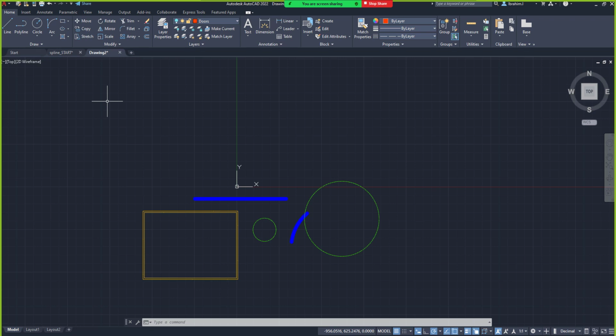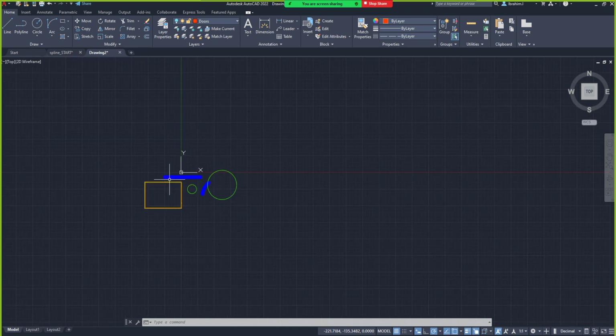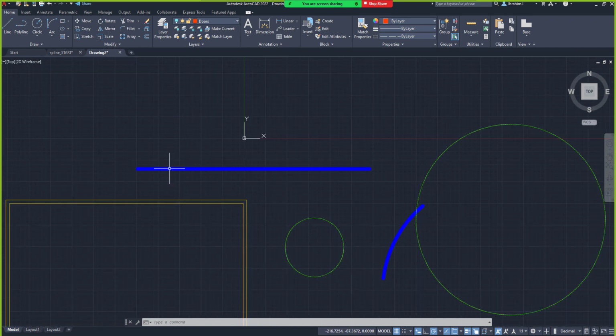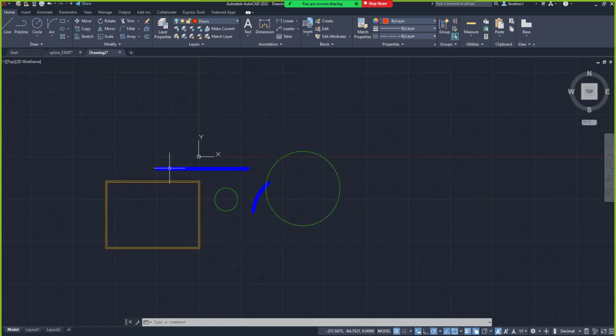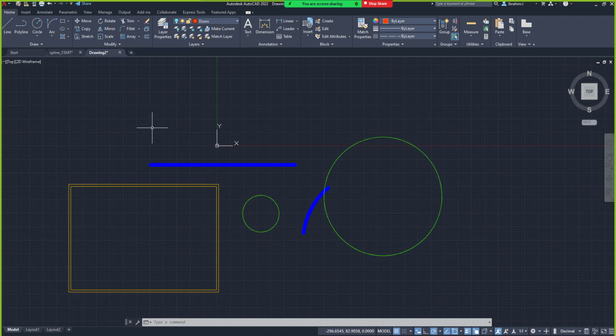Yes. So when you turn a layer off, the normal expectation is that you are not trying to see that layer. So I don't even expect you to draw on a layer that you've turned off. But since you are just getting started with the software, you might have turned it off and you are drawing. You'd be like, this thing is not working. So this could be the mistake. You have a layer turned off and you are drawing, and you are not seeing anything there. You can't have the current layer turned off and then want to draw on that same layer.